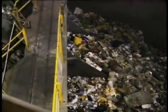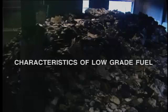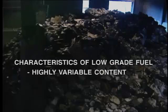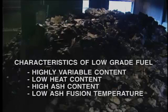In this segment, we'll take a look at combustion equipment used to burn low-grade fuels. A low-grade fuel usually contains one or more of the following undesirable characteristics: highly variable content, municipal waste, for example; low heat content; high ash content; low ash fusion temperature. The effect of low ash fusion temperature is particularly onerous.